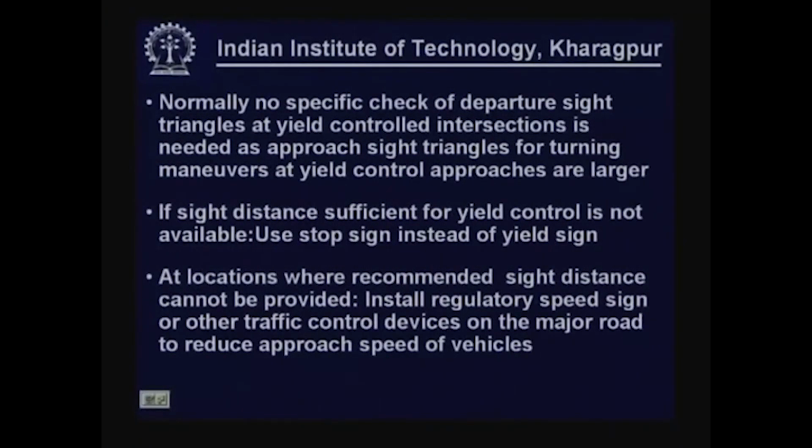But normally no specific check for departure side triangles at yield controlled intersections is needed, as approach side triangles for turning maneuvers at yield control approaches are larger.